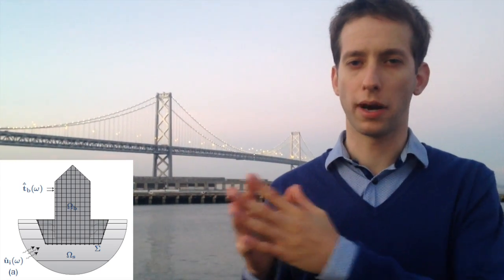A state-of-the-art numerical technique for solving dynamic soil structure interaction problems is a coupled finite element boundary element methodology, where finite elements for the structure are coupled to boundary elements for the soil. This approach offers a large modeling flexibility, but unfortunately at a very high computational cost, especially for three-dimensional problems. This is mainly due to the dense matrices arising from the boundary element method, which lead to a quadratic growth of the required memory when the problem size is increased, while the computation time even increases in a cubic way.